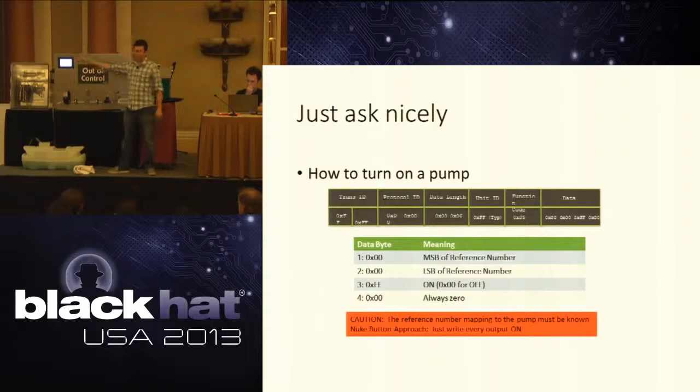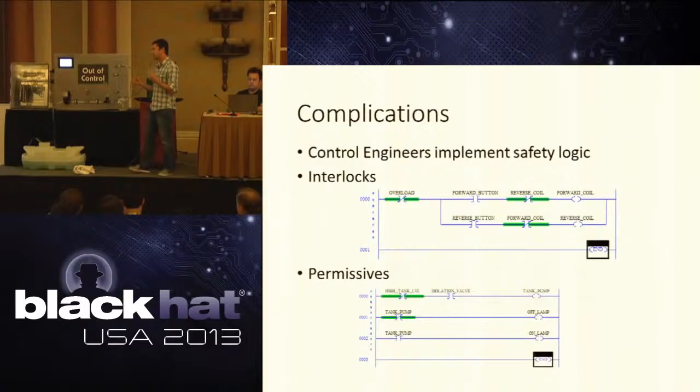So we have a word of caution here, because Modbus is a really ancient protocol. There's not really a way to know what you're driving. All you know is the reference number. So unless you get on an engineering workstation and find the mapping from reference number to a physical piece of equipment, you don't know what you're actually driving. But sometimes you just don't care, right? Sometimes the reference number is in a very specific part of addressable memory, so what you can do is just do the nuke option and turn them all on. We can do that, and we will do that, and see what happens.